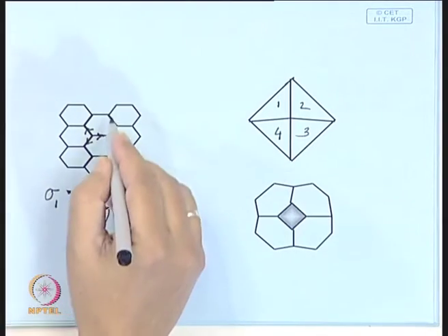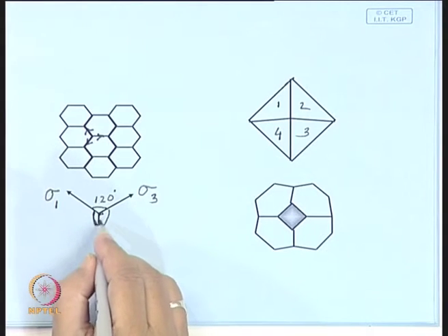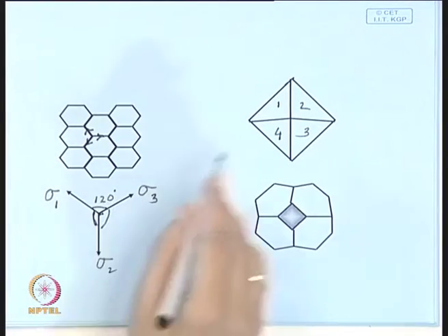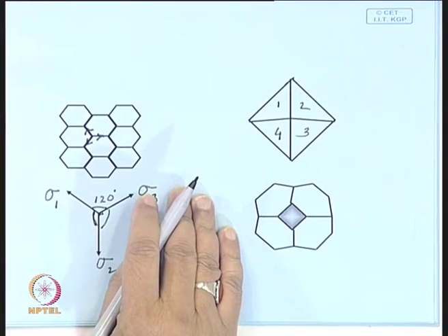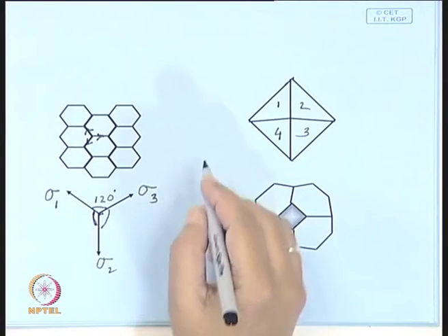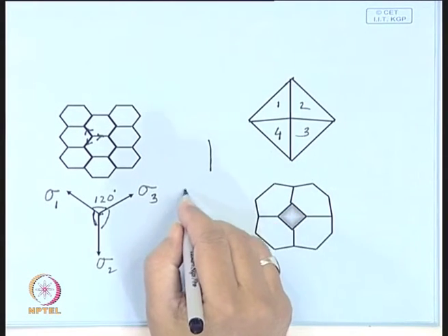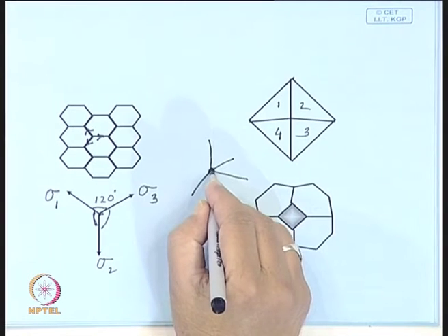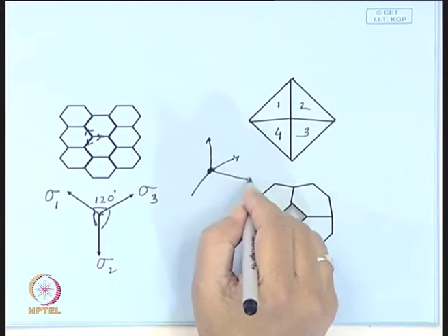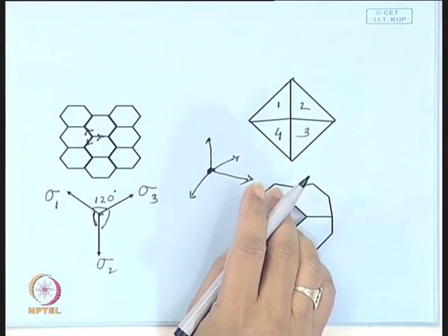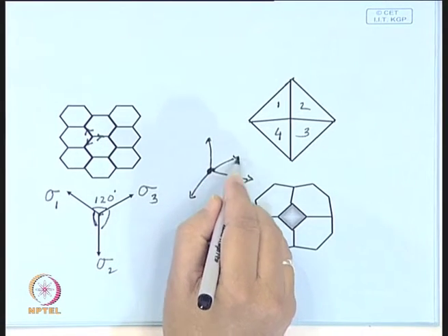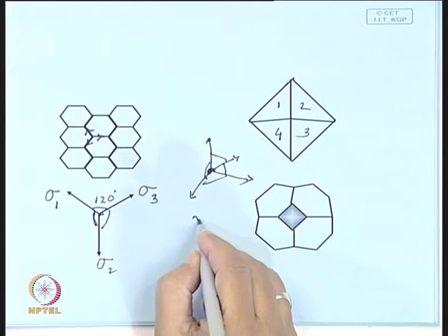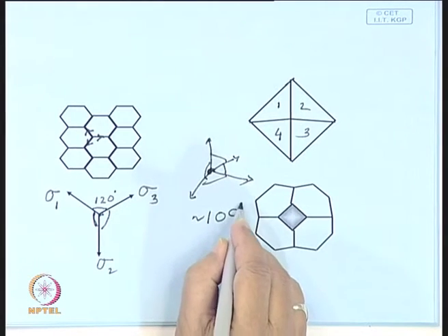Now, there are 2 criteria, one is the space filling and second is that the equilibrium of the surface energy, or surface tension equilibrium, must be maintained. Now, when these surfaces meet, there will be a grain boundary, and now in 3D, it is quite likely that in many places you will have one this, one this, one this. So, there will be 4 points, like if you try and recollect the carbon bond structure, if all these energies are nearly equal, the angles have to be equal, and I think we said that this angle is around 109 degree or something.